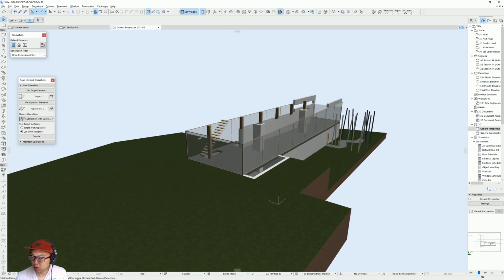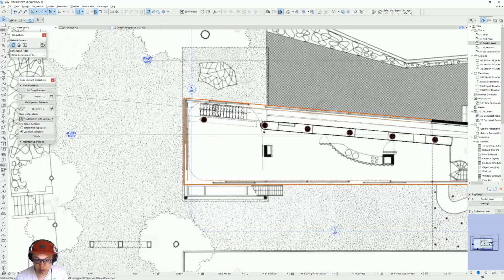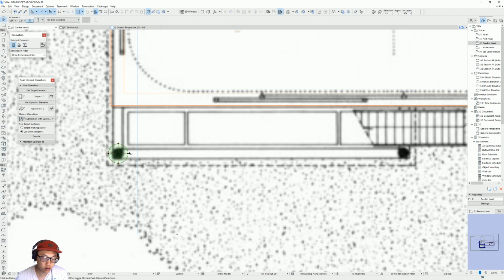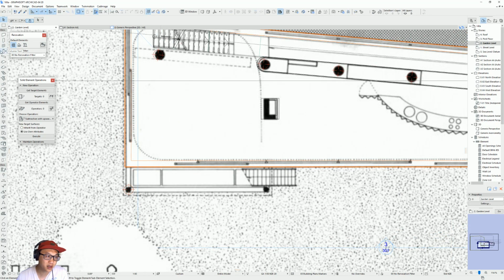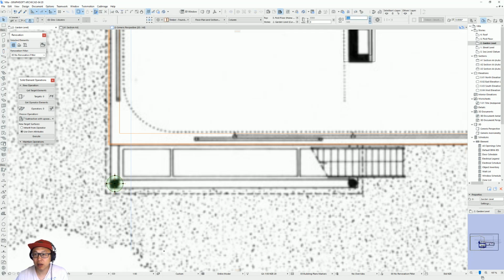and I'm missing a column there, or two columns. So maybe just add that quickly. So I'm just going to take this one, put it there. So what I just did, instead of clicking the column tool here, I just absorb the properties, so we automatically activate that column tool like that, and maybe 250, and maybe I'll try to just center it, the wall 350, so 175 up.